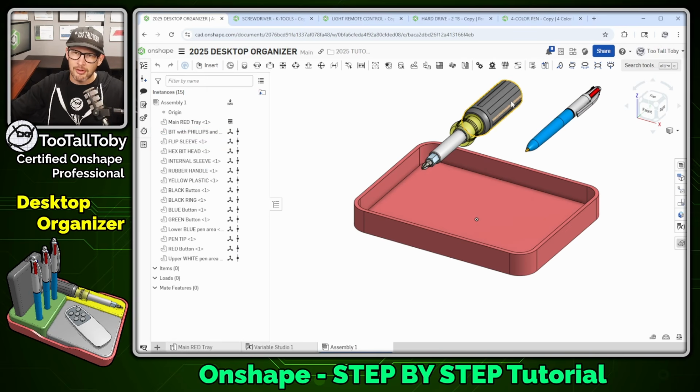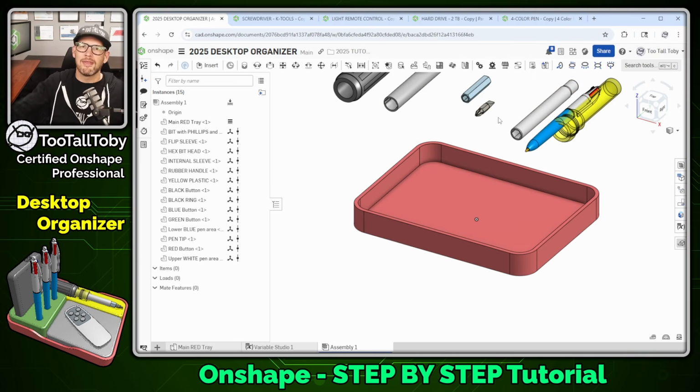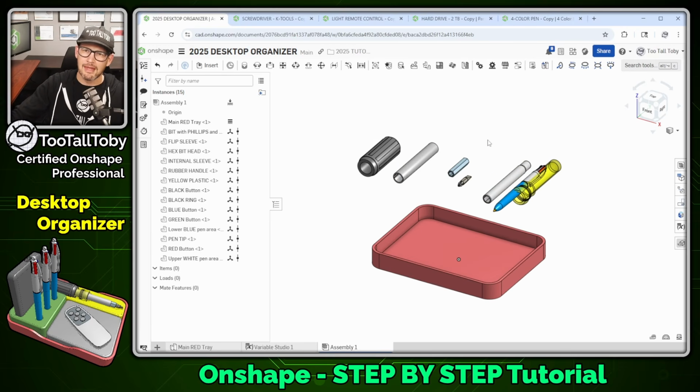And you can see that I'm able to grab these components and just drag them apart. They don't stick together. It doesn't really behave like a sub-assembly. This isn't really what I want. Ideally, we would want this thing to behave like a sub-assembly. So to accomplish that, let's make an assembly in each of those documents.